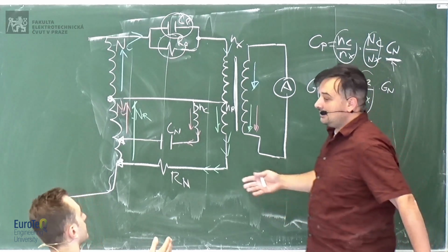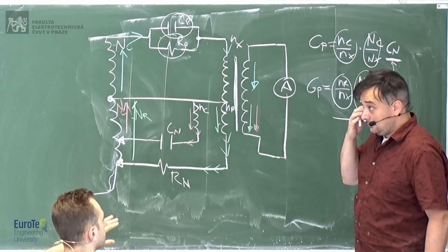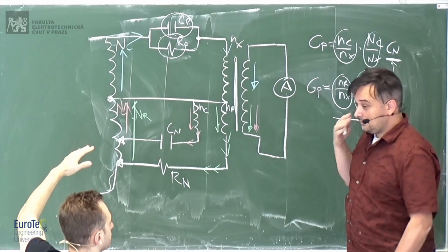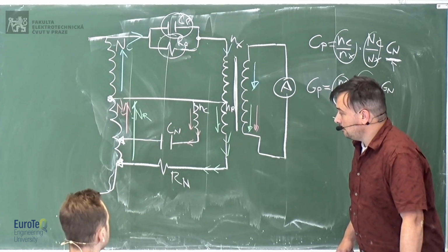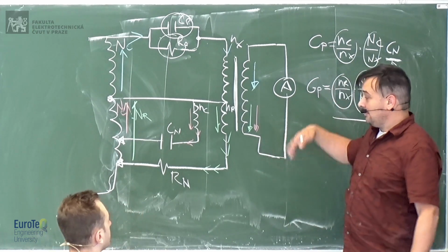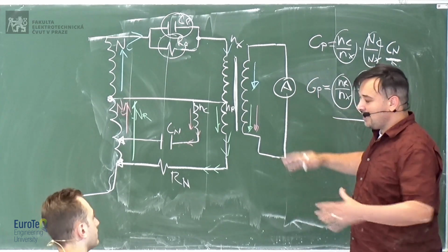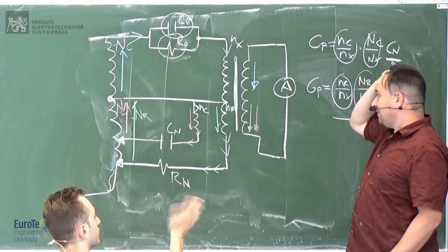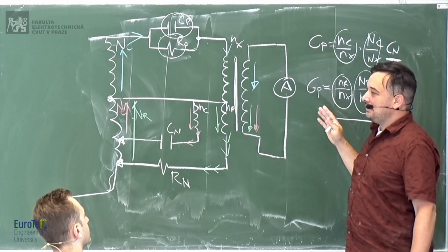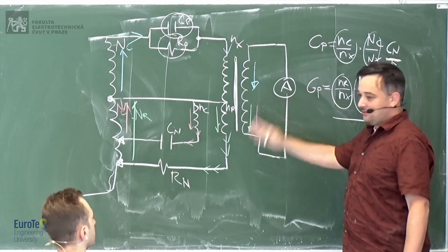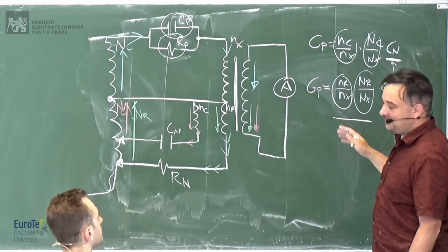Also because if you're doing a bunch of measurements, that uncertainty would be in all of them, so it would sort of cancel out, right? It would be like a universal offset. So if you're measuring a bunch of capacitors and resistors, and you keep everything in the system constant. In this case, I was just saying if you want to characterize a production line, then the uncertainty is in all of them, so it sort of balances out. I think this kind of circuit is used to measure really one piece. If you want to measure a batch of production, use much simpler and less expensive methods.